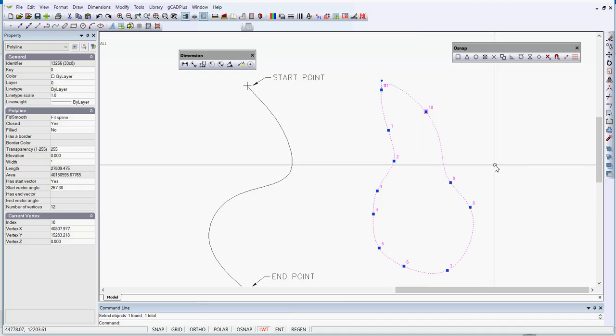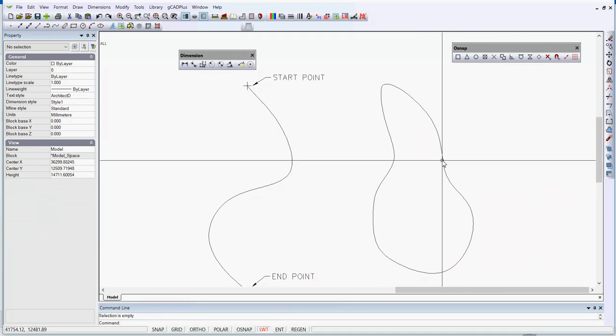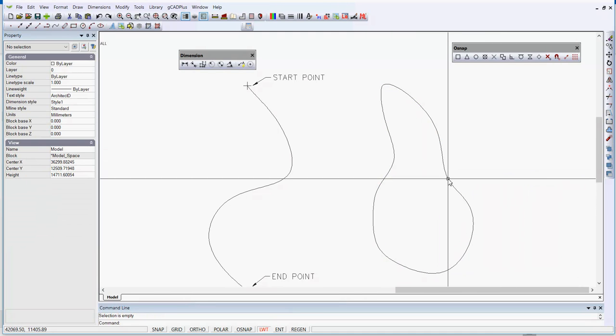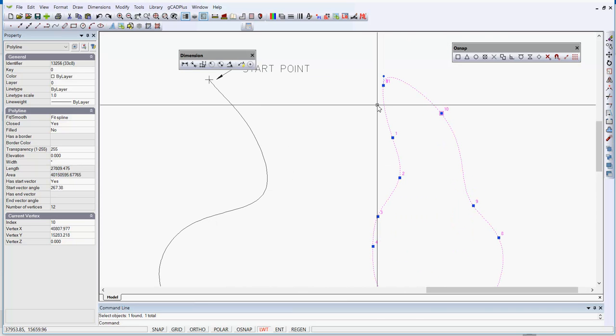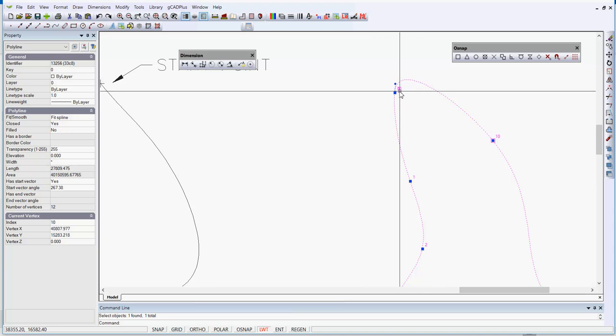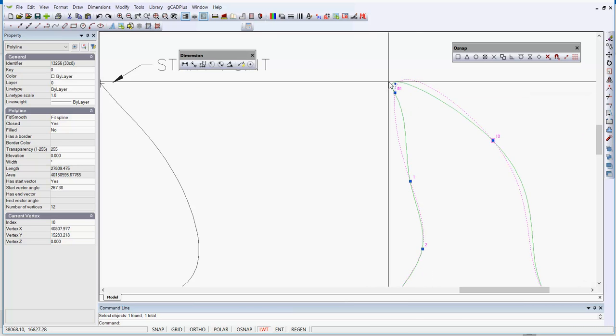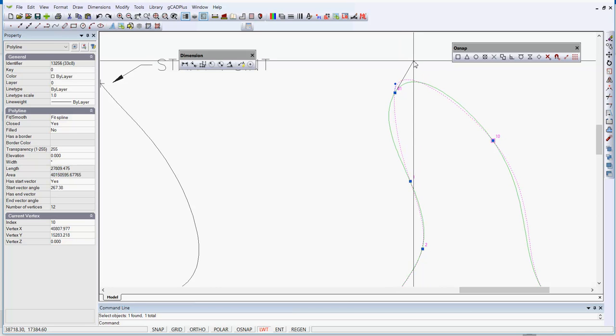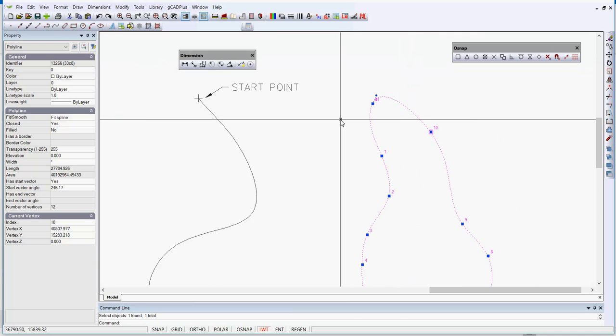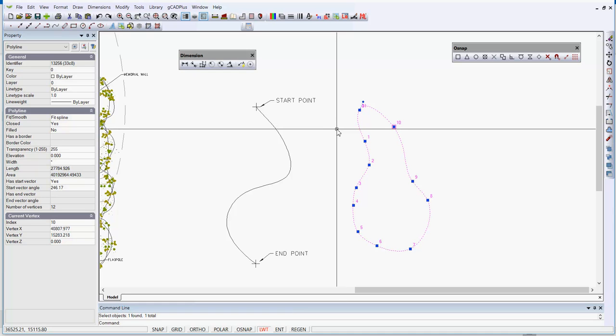I'll unselect all. So there's a closed polyline drawn using the spline command, and unlike a normal polyline, you've still got a little opportunity to tweak things like so as I move that around. So you can use this system to get some quite nice shapes of that polyline.